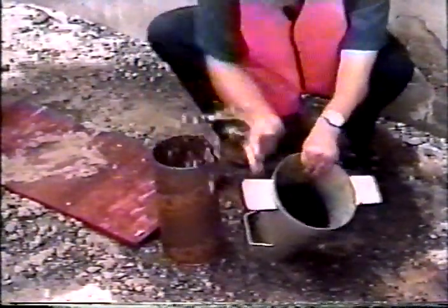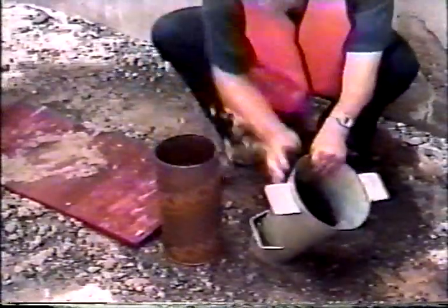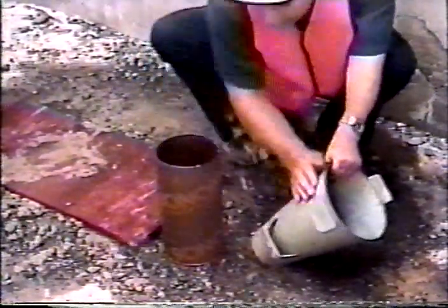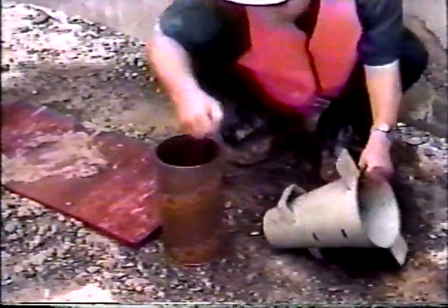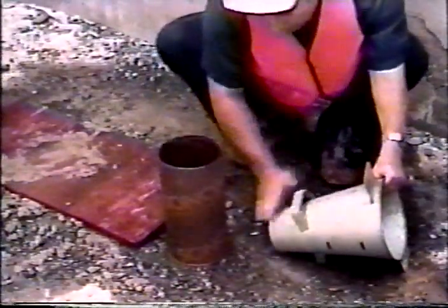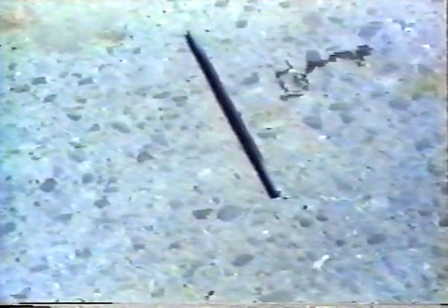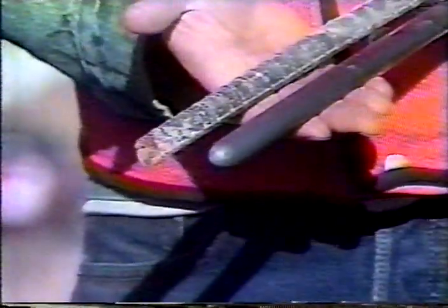The surfaces should be smooth, with no dried concrete on them. Also, there should be no major dents. A standard tamping rod is smooth with a rounded tip. Makeshift rods, such as cut-off reinforcing bar, are unacceptable.